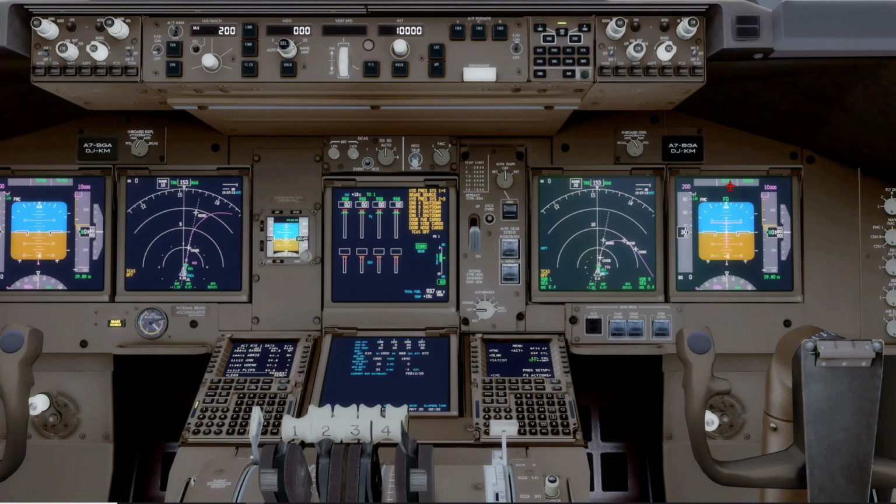We're checking blank, TOGA, FD, 8 degrees pitch up, wings level, 30 knots, parked, ground speed 0. No flags, heading's good. We've got the altimeter set right now. And for general status, you're looking for mainly no flags.